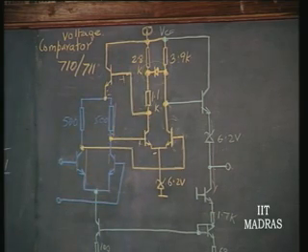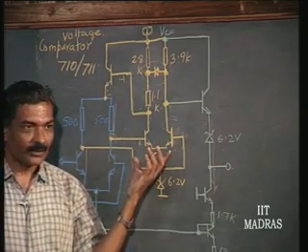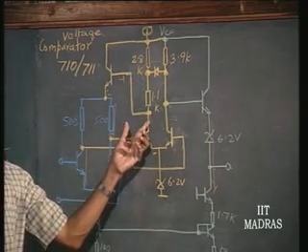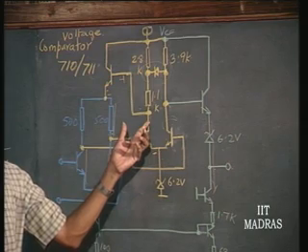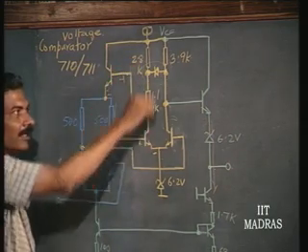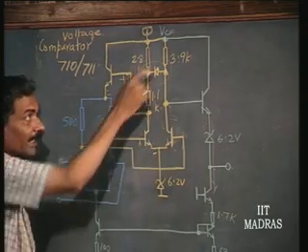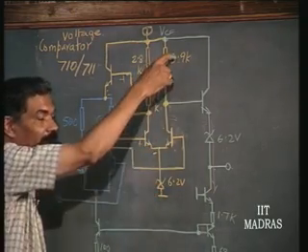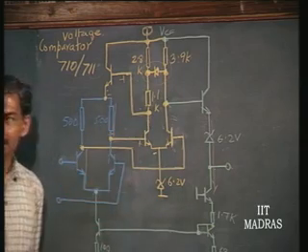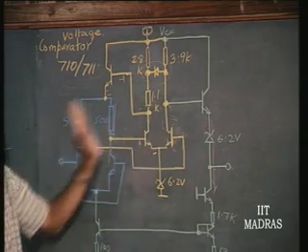You have to come in an indirect fashion here to find out the operating current of these common emitter amplifiers. Okay. So, the operating current is fixed because of this potential getting fixed here. So, this current is known, and therefore, this current should be same as this current. Okay. So, you know the gain of this stage, which is 3.9 K divided by RE of this transistor. Okay. So, overall gain is that gain into this gain.